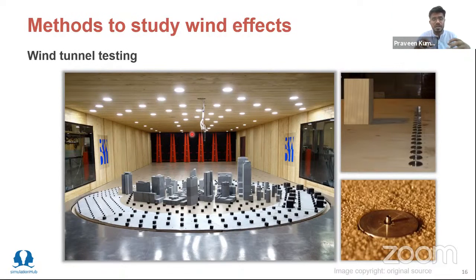These are exposed to scaled-down wind velocities. These tests are conducted in what is called a wind tunnel, and probes are installed at certain places to measure the wind velocity and pressures. When we do this study at a large urban-area level, scaling is a problem.